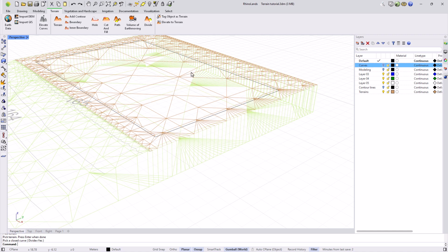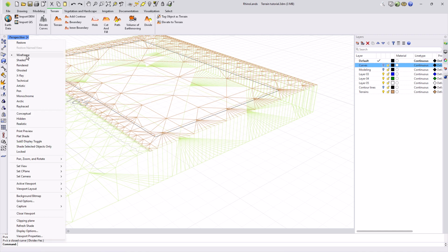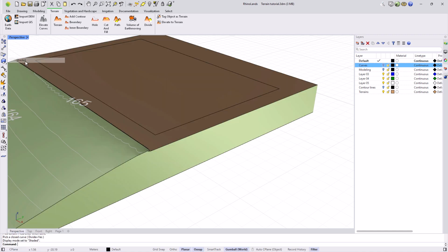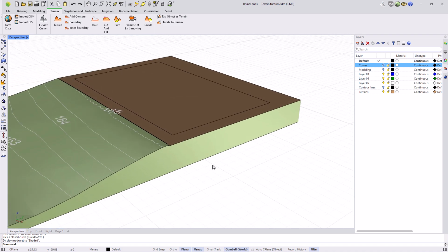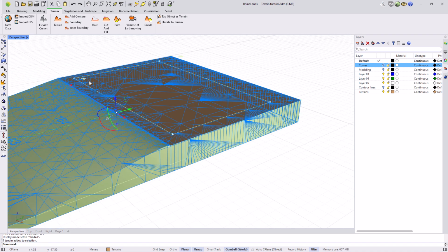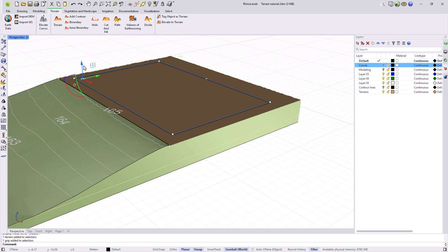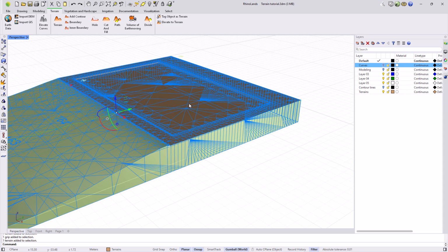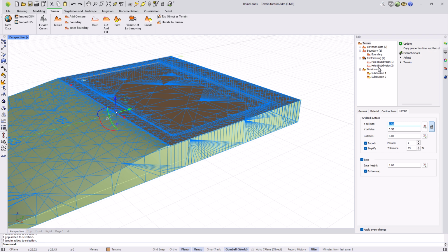When it comes to selecting hidden curves for the terrains, the wireframe visualization mode really helps us see and select elements that would otherwise be hidden. The elevation of the curve is what will determine the depth of the hollow. Any terrain operation can be edited. We can move the height or position by looking for its handle. Or we can also modify the position of the control points.